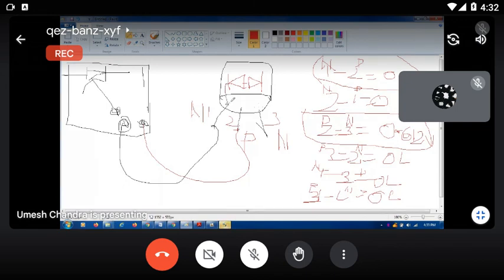Now this side is connected to 1, and the middle is 2. Now see the first point, 1 to 2, where you got some voltage. That means the negative probe is connected to the negative of the diode, and number 2 is positive, and the red probe is connected with the positive of the diode. Then you got some voltage. Then another case, reversely, 2 to 1. Here 2 is negative and 1 is positive, but actually 2 is positive and 1 is negative. This is the reverse bias.